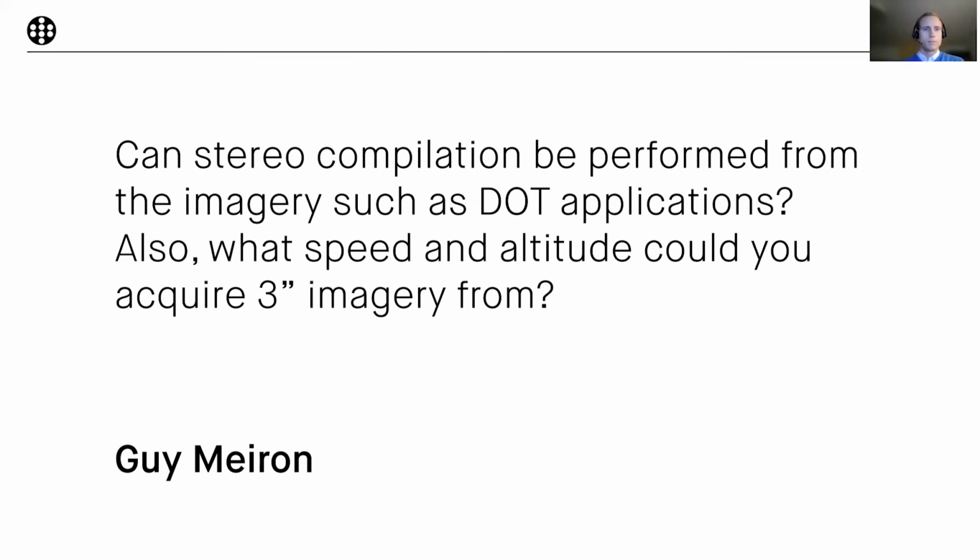Yes, so for the first part of this question regarding stereo compilation, due to the camera concept of the Condor, there are some limitations to the stereo capability. The panchromatic image channel has a very high overlap, and therefore this would be usable for creating stereo models and doing measurements in stereo, but this has the limitation of the low resolution. The RGB channel, in contrast, has the high image resolution, but quite limited image overlap.